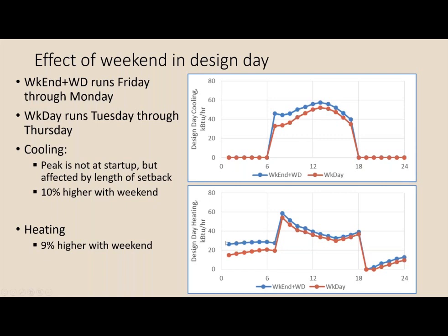And the bottom one is heating, so you get bigger peak loads for both cooling and heating when you include that weekend. And it's a pretty big difference. It's 10% for this model for cooling and 9% for heating. So that just shows that it's really pretty important to include the weekend when you set up your design days.